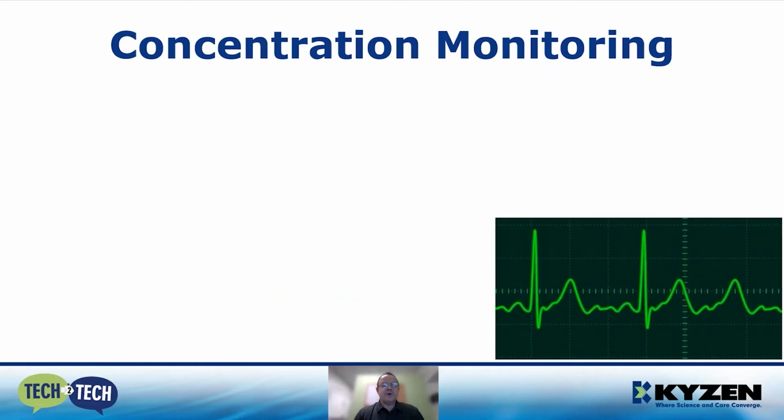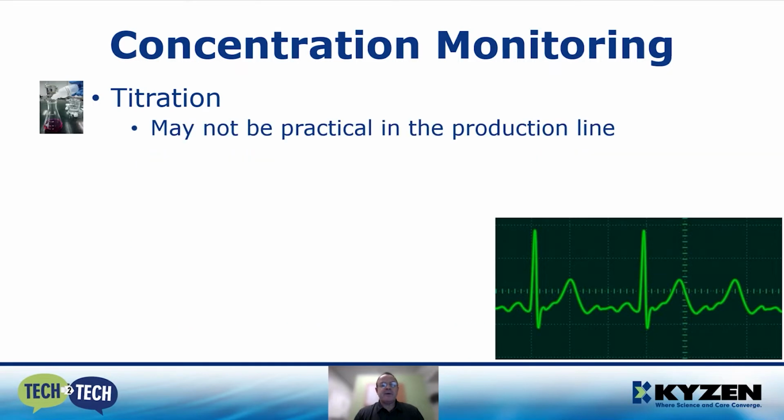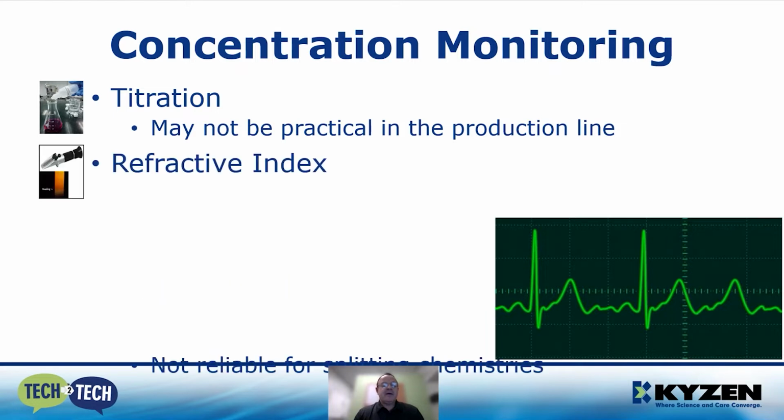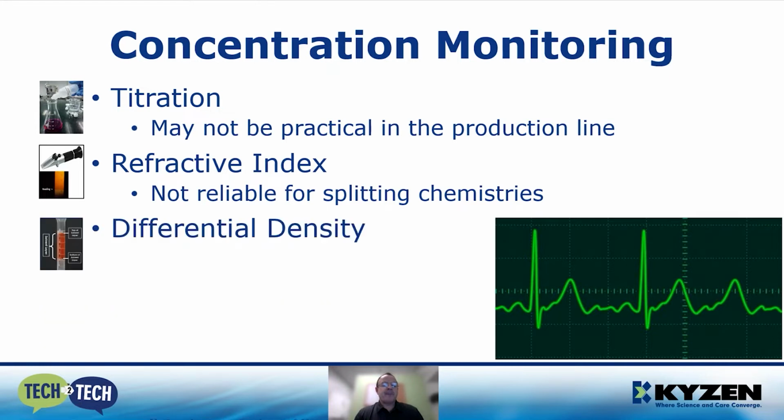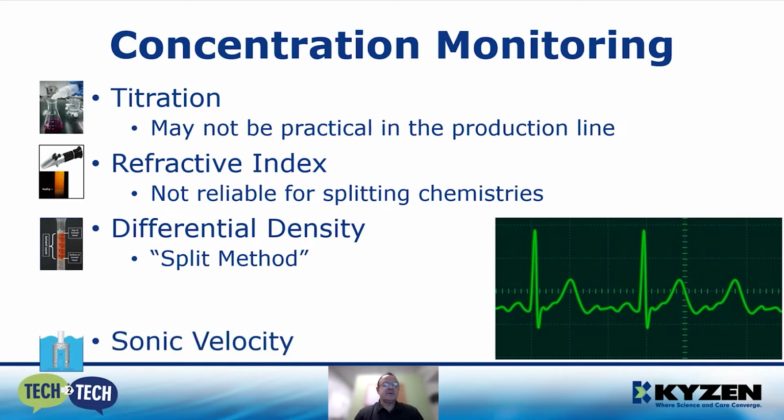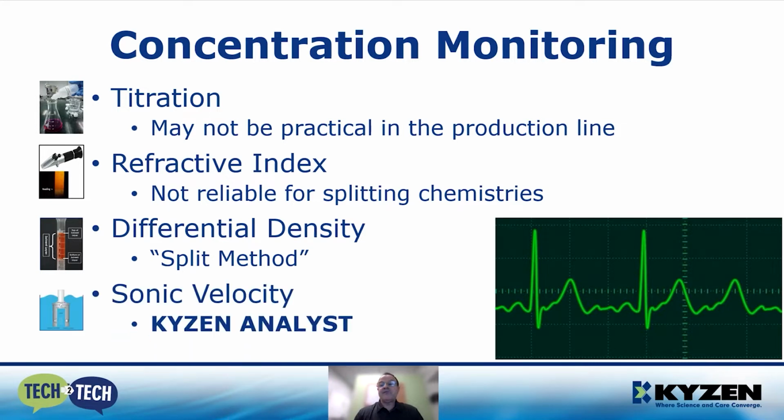Looking at concentration monitoring, we have different methods. Titration, which is not really practical in the production line. Refractive index, which tends to be not very reliable for splitting chemistries. Differential density, also called the split method, where we are measuring a layer of the solvent. And sonic velocity, which is the main focus of this presentation.